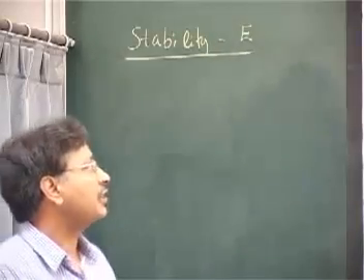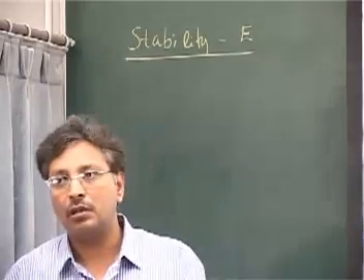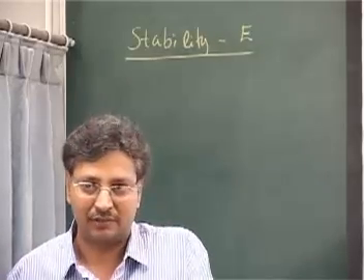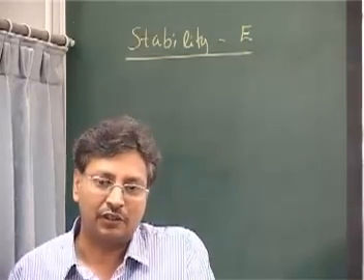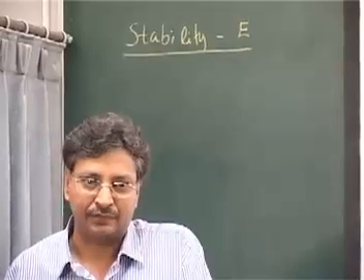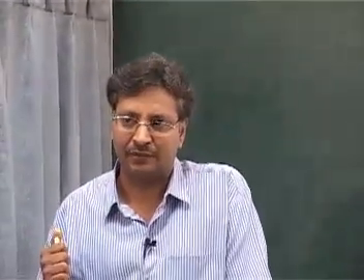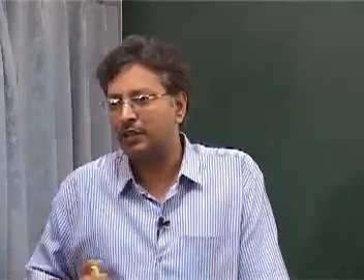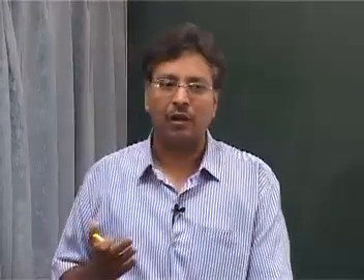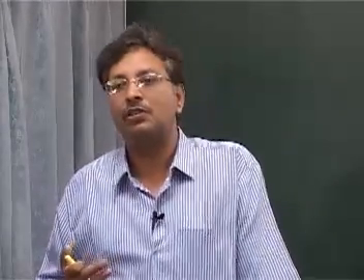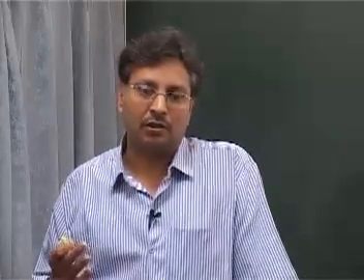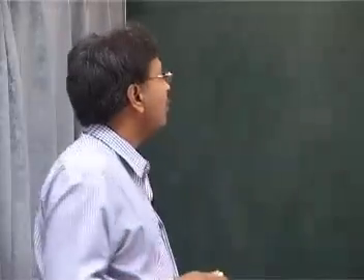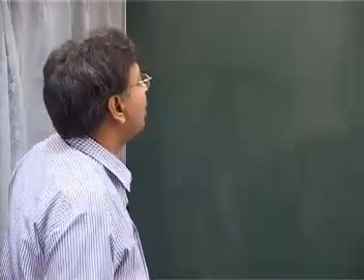Let me ask you, suppose the day is very heavily overcast, lots of clouds, and of course the wind speed is moderate, 3-4. What stability do you think it will be? When you have lots of cloud, the normal stability you take is about D, the neutral conditions. Okay. The stability is E. All right. Then what do I do?